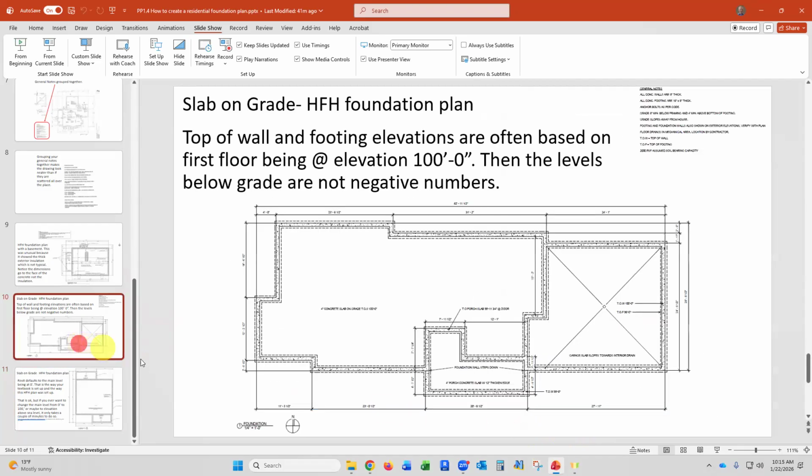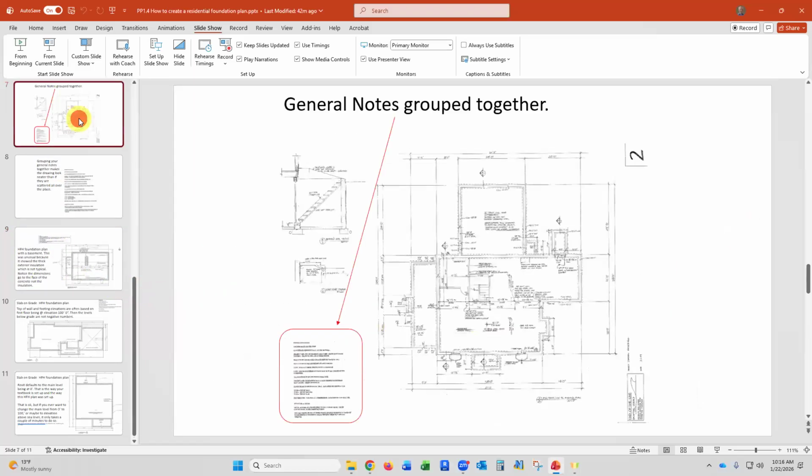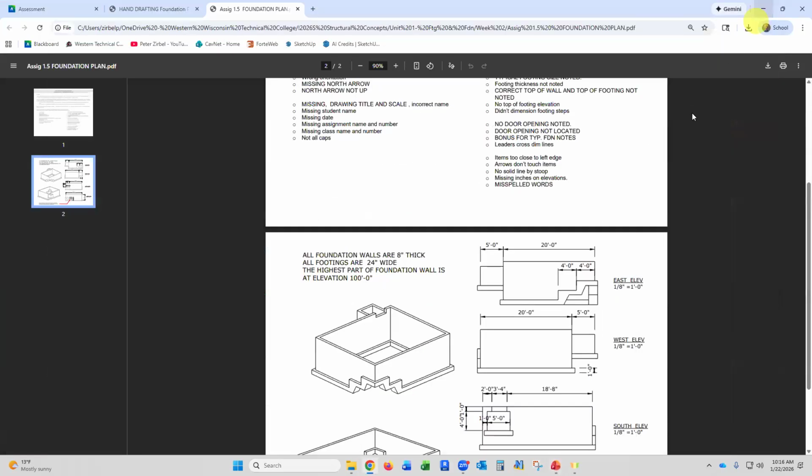Let's see if there's a drawing title on this one. Same deal. Foundation plan, 1/4 inch per foot, north arrow next to it. Let's look at this one here. Title, north arrow, where's Waldo? Okay, so there's an example of what not to use. You have to search over the whole drawing to find it. Now, I'm going to be embarrassed here. I forgot the north arrow on my parents' plan, so that one I screwed up. Okay, so now let's keep going here.